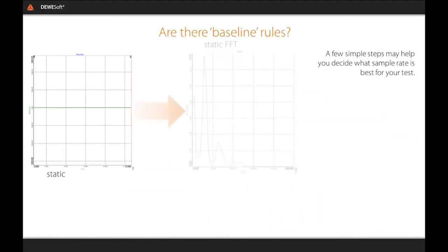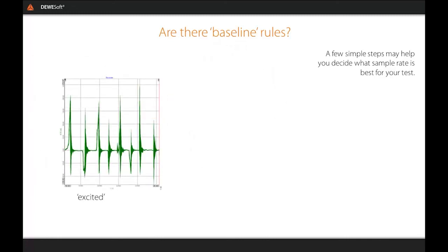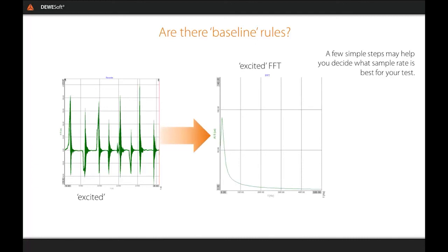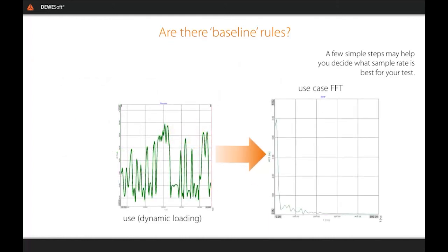And now that we have our data, we can perform some very quick FFTs on the test data. Firstly, the static, then the modal, my apologies, or the pseudo-modal, the one that I excite by tapping it with a hammer. And then finally, the mechanically excited data.